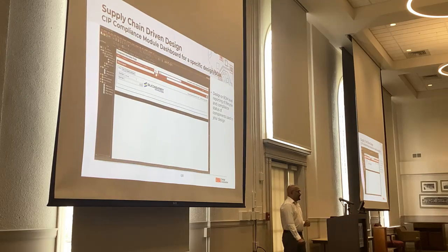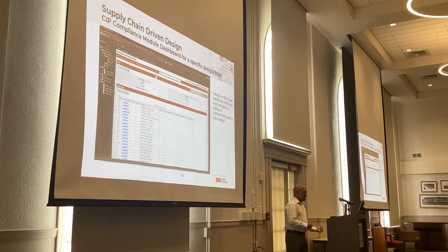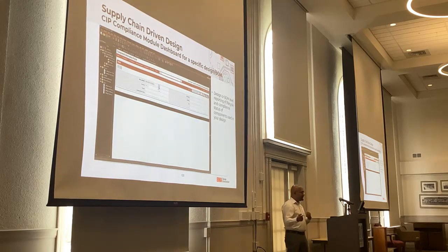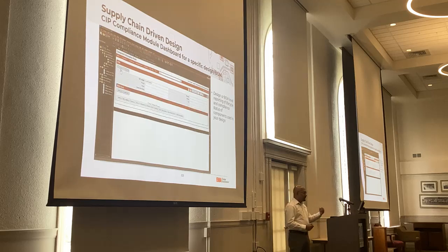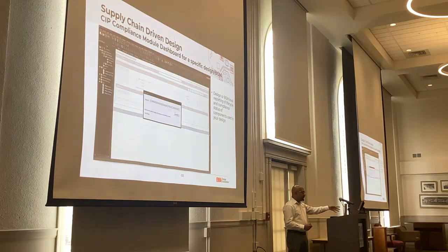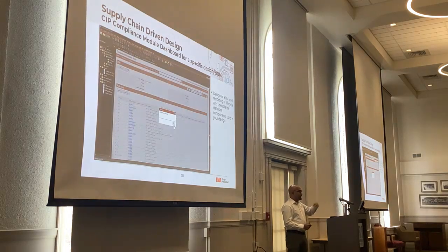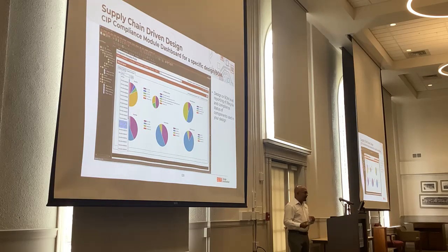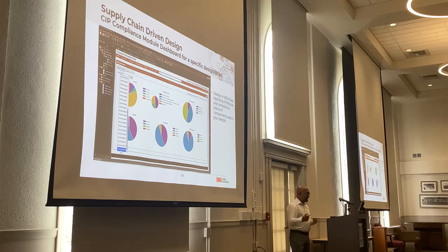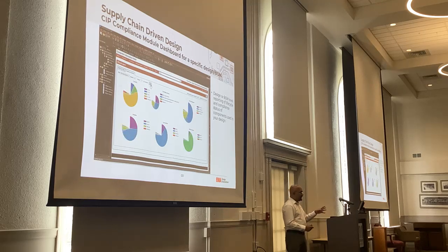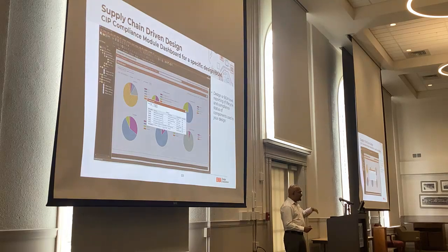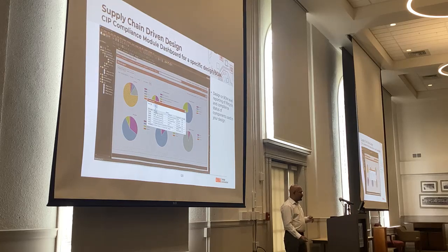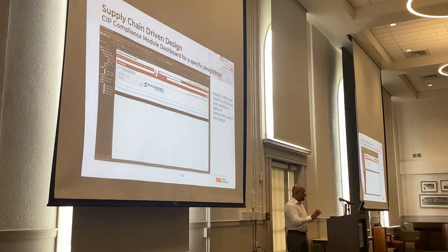Okay. Now let's say you're working on a design and you want to run a report on that design, right? So OrCAD CIP will allow you to, this is the design that's already open, so it can natively pull information from that design into CIP and run that exact same report, not at a library level, but at that design level. So what you're seeing there is it pulled the BOM from the design and compared that data against Silicon Expert. And it shows you the same exact report, but at the design level.